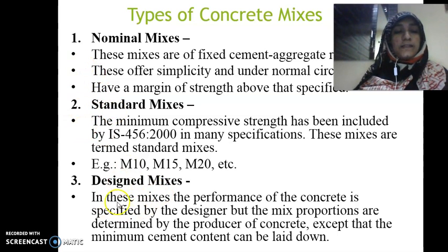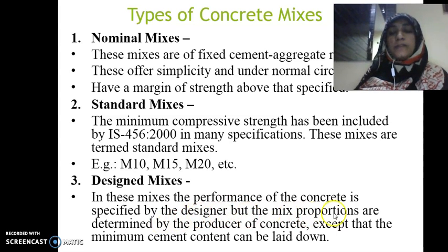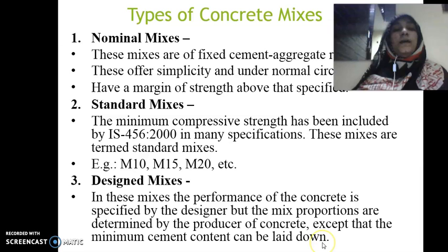In design mixes, the performance of the concrete is specified by the designer, but the mix proportions are determined by the producer of the concrete, except that the minimum cement content can be laid down. What is design mix? In design mixes, each and every ingredient of concrete is first tested in the laboratory. But in nominal mixes, the properties of ingredients are not tested in the laboratory.